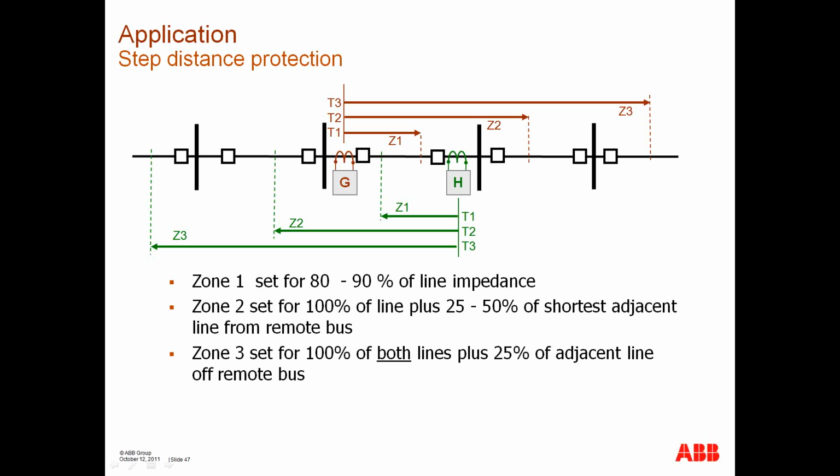I believe the new generation includes positive sequence and memory, such that the factors are weighted, that you have 15% memory and 85% of the positive sequence quantity is used, such that if you were to measure zero voltage, you would at least have the 15% of what existed before the fault. I hope that answered the question.